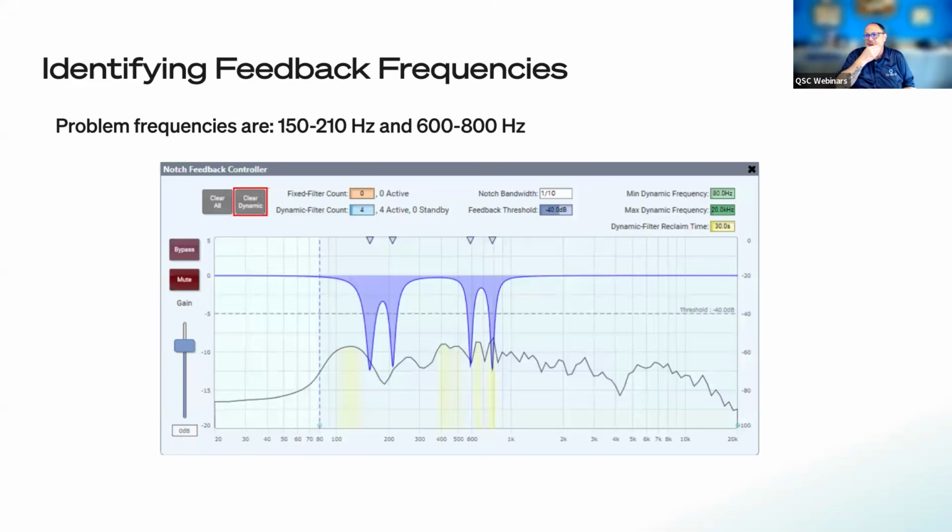So here's what that looks like. Just like I was saying, you set your fixed filters. These are filters, a tool that you can set into a system, and it will automatically notch out the things you want to. Now, the true audio people are going to say, well, if you set the room up right... Yeah, but if it's a public space, accidents happen, people point microphones in the wrong place and things like that.